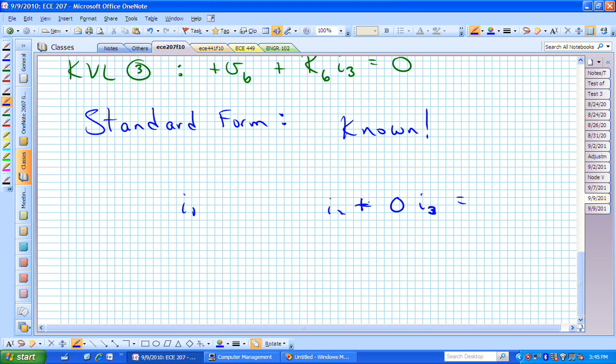What did we just say? We said we had an R1, an R2, and an R sub 3 touching I1. Those come in with a positive. We had R sub 2 shared between I sub 1 and I sub 2. R sub 2 then comes into the I sub 2 coefficient with a negative sign, and we said that V sub A should be positive on the right-hand side. And if we go and collect terms from our very first equation, it should be consistent with that expression.